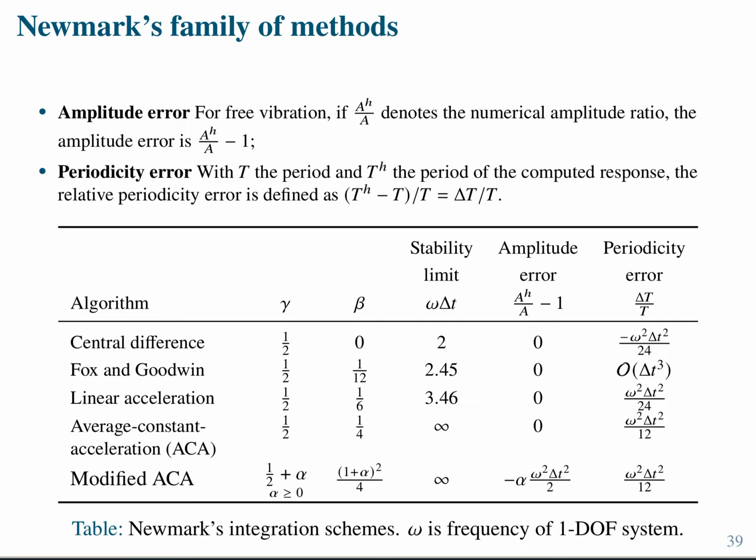There are many types of nonlinearities. Just looking at one type, material nonlinearity, it is not so straightforward to obtain the solution using Newton-Raphson so that it converges nicely, quadratically. You need a properly derived, consistent tangent matrix, and sometimes that is hard to do. At fracture, good luck. At contact, contact is the worst of the nonlinearities out there. In fact, every nonlinear finite element package out there performs very nicely for material nonlinearity, but try to solve for contact. Good luck.